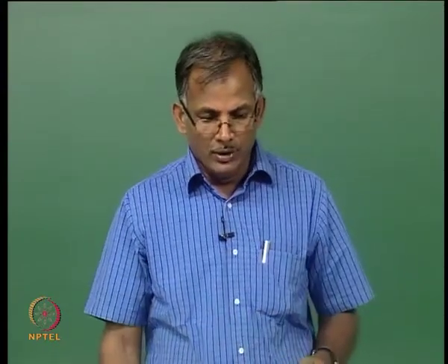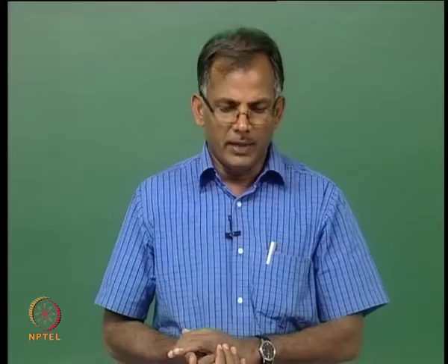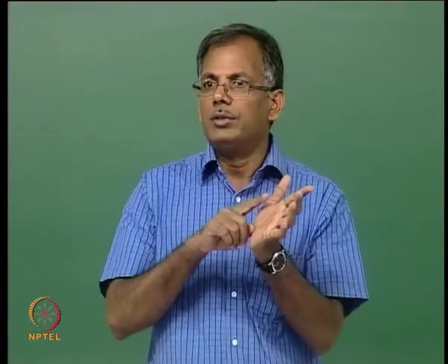Can we do repair works, something similar to adding additional piles, or do we have planned activities? And then finally we will come to the connection between the pile and this jacket. I think one of the connections we have already seen, the skirt pile connection with grout between the annulus of the leg and the pile, we have already seen in the previous session.